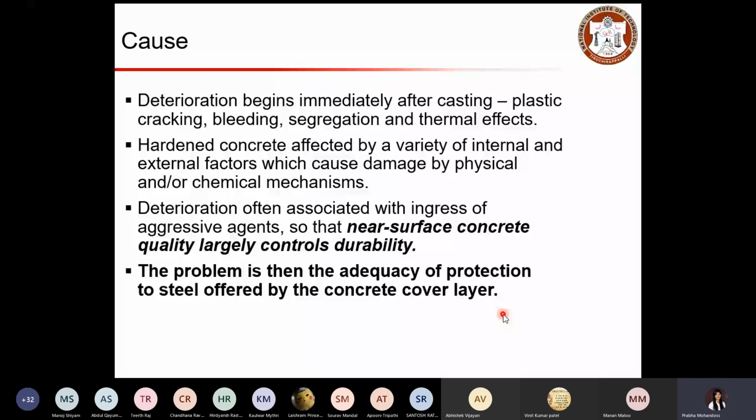So the steel will help your concrete, or the system, to take more tension also, by enhancing its capacity, and it undergoes a lot of energy absorption before the member fails. So the ductility will also be increased when you provide reinforcement.